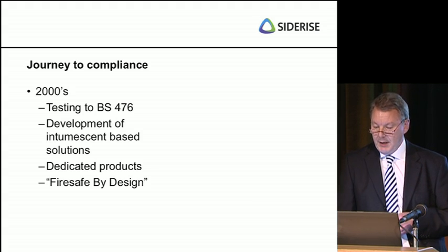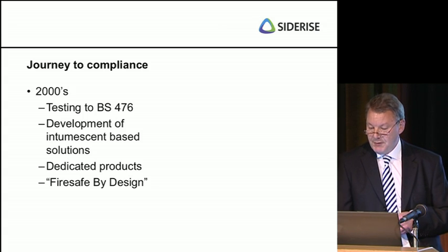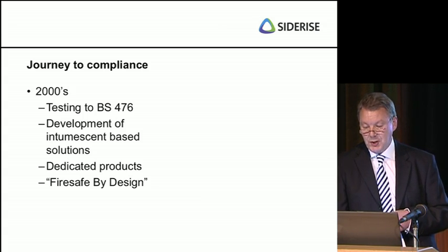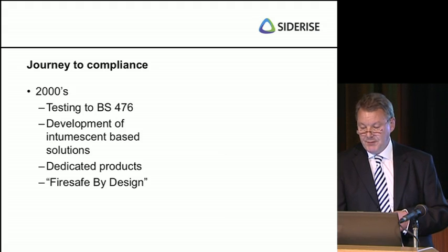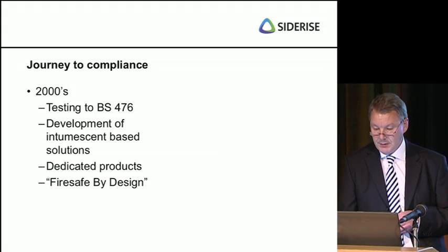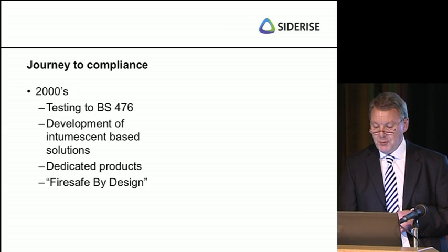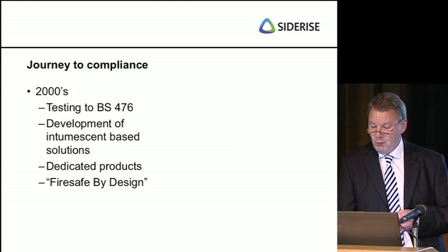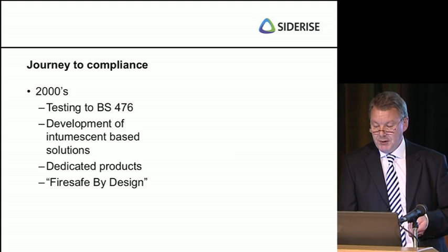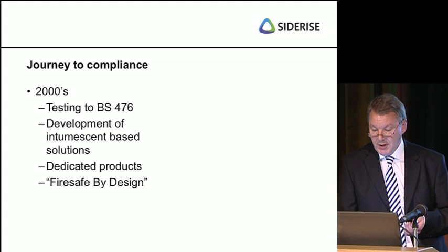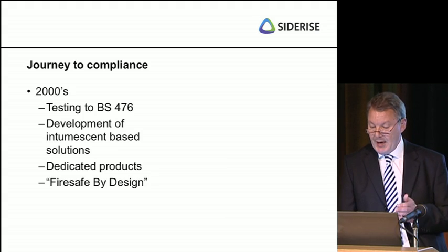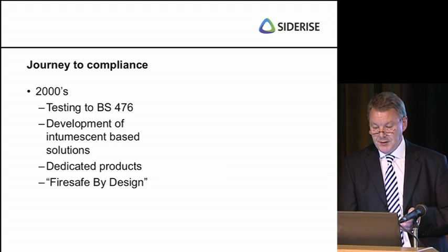With the maturing market and an ongoing sense of dissatisfaction with ad hoc and assessed products, we began the development and testing of dedicated intumescent-based products. Our motivation was to provide a hybrid material that would maintain the desired ventilation cavity, allowing the rain screen to function, until such time, or rather such temperature, that the intumescent material at the outer edge of the barrier would expand to seal the void in the event of a fire.